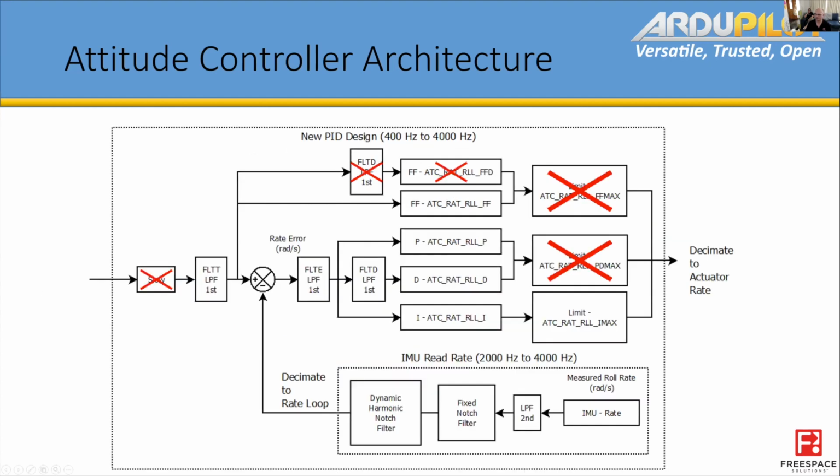So you can see here that now with the new filtering, we have this D-term filter separate to the low pass filter. I have found this really useful for vehicles suffering from high noise. It's another tool to knock off the high end noise. It's much better if that noise isn't there, but often when people come to me with aircraft, they don't understand where they need to make improvements.